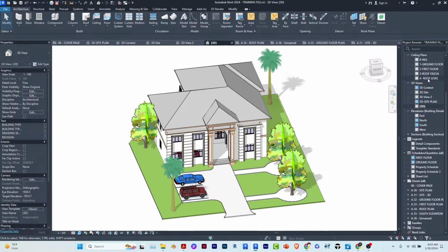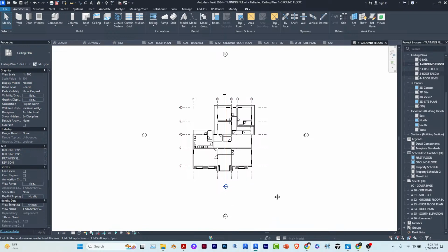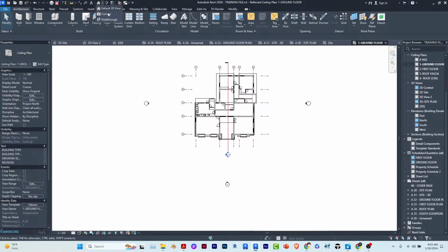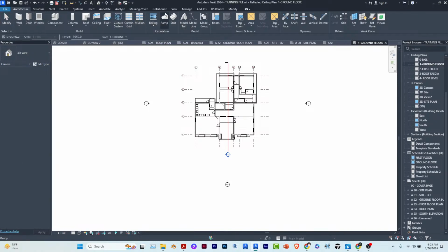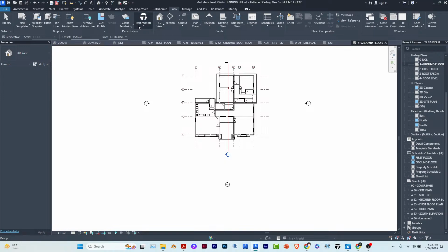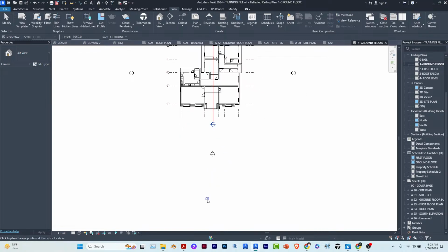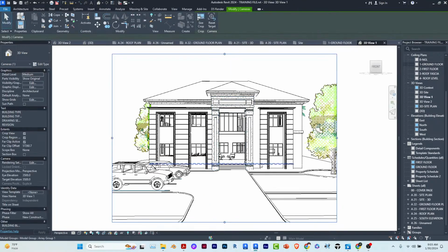So the first thing I want to do is to take your camera shot. I have an existing camera shot, but nevertheless, you might want to start with a basic one-point camera perspective. Under this home icon here, you click camera, or you can go to view, and under 3D, you click camera. But there is a shortcut here, so you can just come here, click camera. And you can start on the ground floor with a normal front elevation shot, something of this nature.